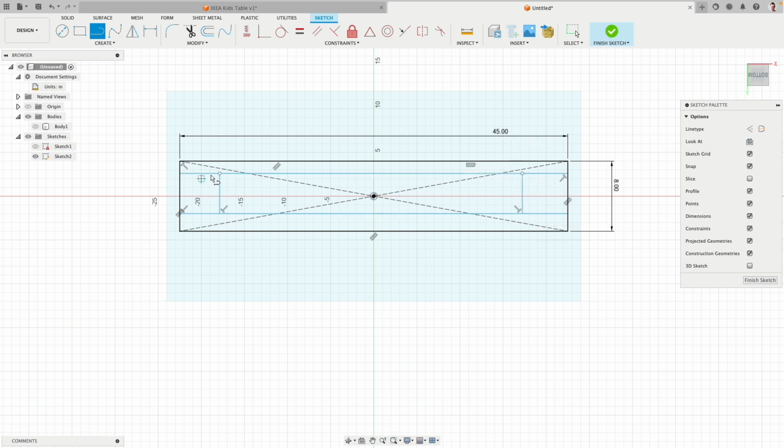There's actually, and there too, a sketch issue. These points weren't really glued onto the line. That's actually this coincident constraint. So you can just snap the point directly on it, or how I did it here, you just drag it back onto it. Very good. Let's add some dimensions.